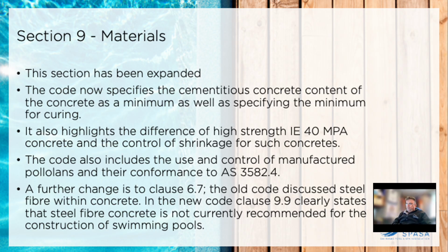It also highlights the difference of high strength concrete, i.e. 40 MPa concrete, and the control of shrinkage for such structures. So essentially, as you get to higher grades of concrete, or you get to pools which are fixed by other structures or other bits and pieces, and they want to shrink or move away from them, it's very important. Shrinkage is a very important component to be considered, both when you're doing your pricing and costing, but also in design.